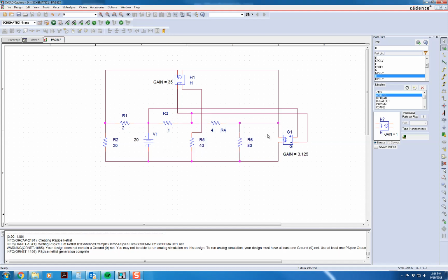Okay, we're back here. What I went ahead and did was just closed out of that simulation. Alright, now we're really back for certain. Alright, so what did I say I forgot to do here? Well, I forgot to place a ground, which is why I get all sorts of simulation problems. So I need to put my ground here and connect it up. And now I'm going to simulate, but I will again pause the video.